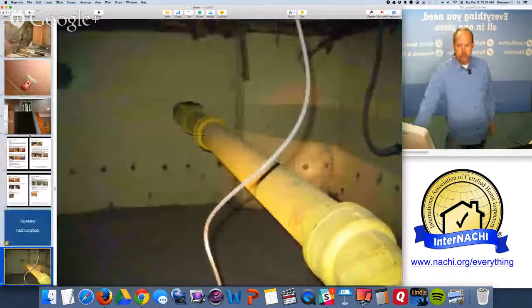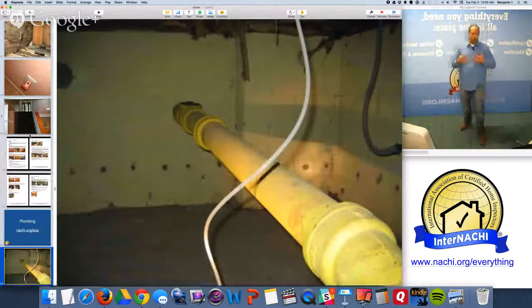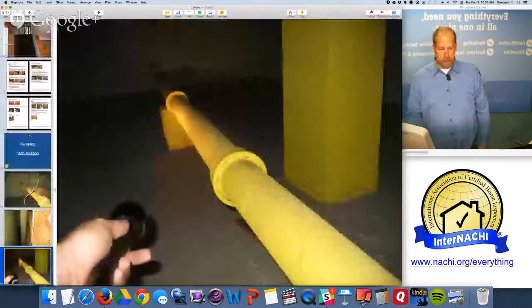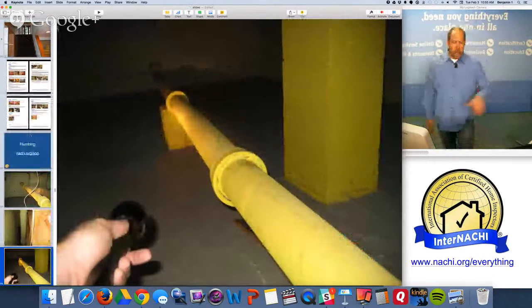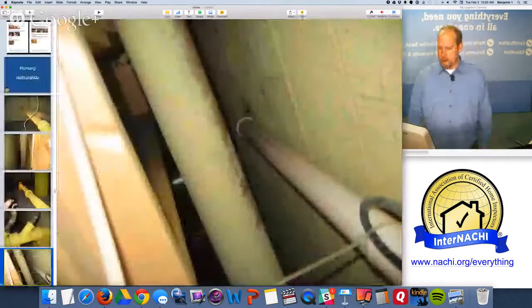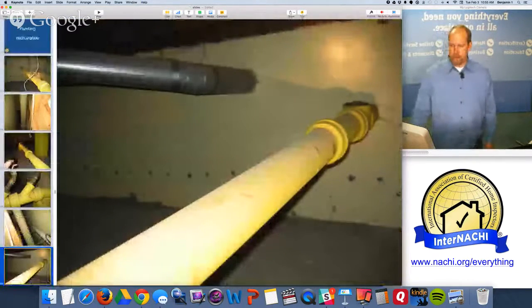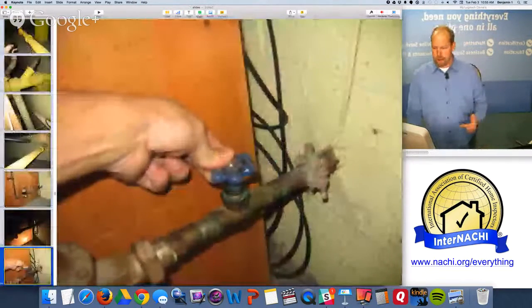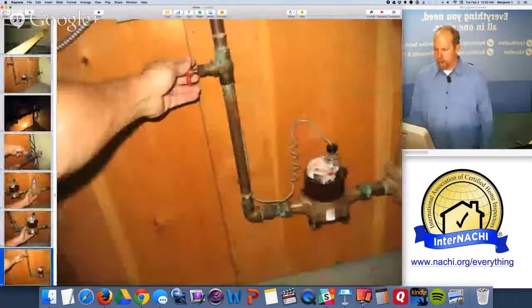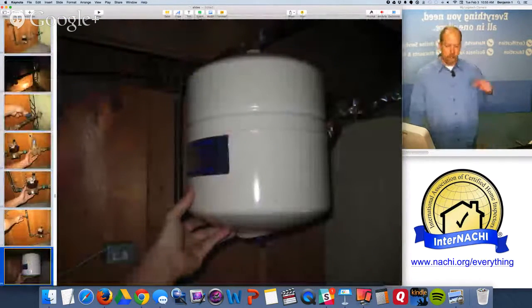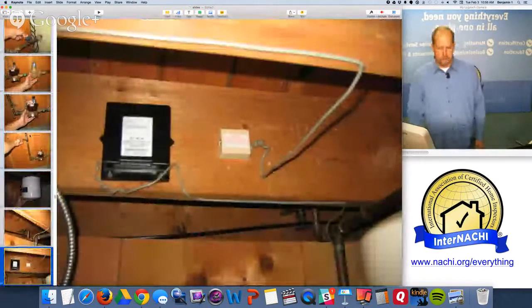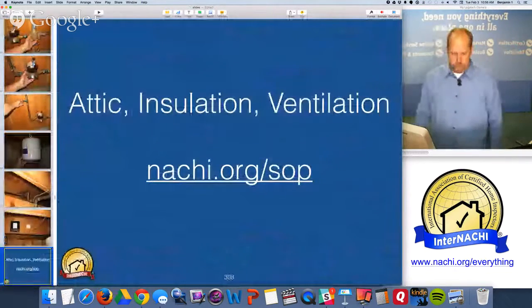So the plumbing, you want to think of water again: water going out, the sewer line, drain and waste vent, and the water supply coming in. In this house, northeast, they use a lot of cast iron. I'm looking for cracks down the line of the cast iron. Everything looks pretty good. Sump pump discharge, dryer vent exhaust, water coming in, shut-off valve, pressure regulator, water meter, water shut-off valve, missing jumper cable, jumper line, pressure regulator, a drive-by water meter sensor.